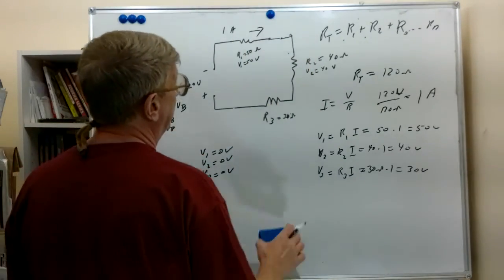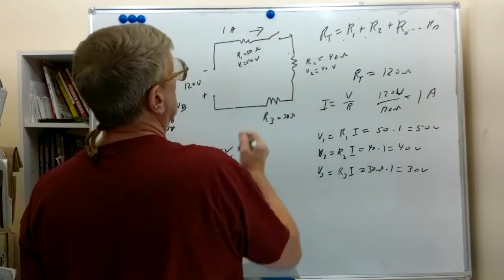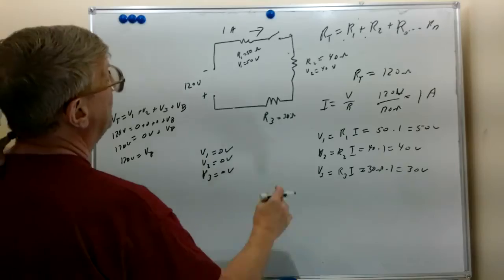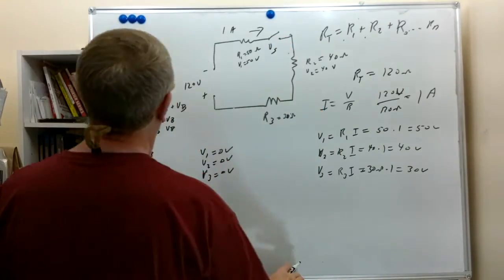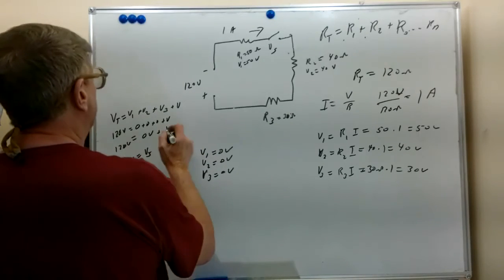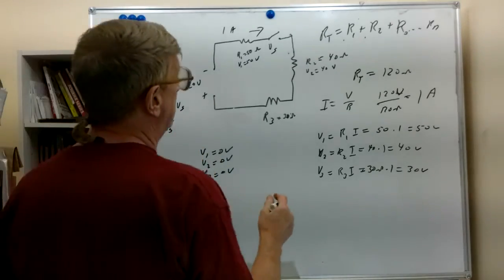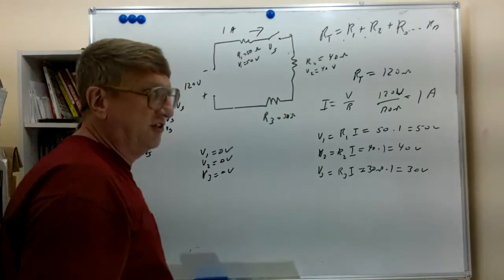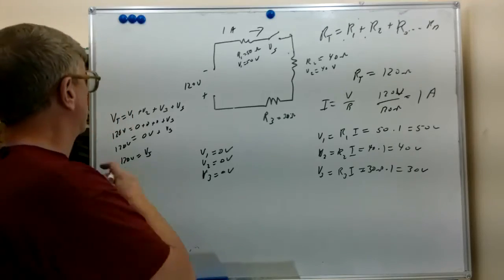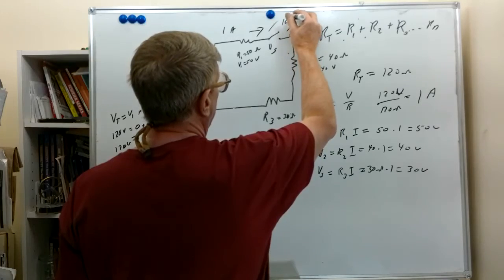But if we open the switch, all of these voltages go to 0, and now instead of calling it VB, let's call it VS for V switch. And we'll change that thing here to say VS. VS, V switch. So what we're getting down to is an open switch in a series circuit like this. All of the supply voltage will appear across that open switch. So if we put our meter here, we read the full 120 volts.